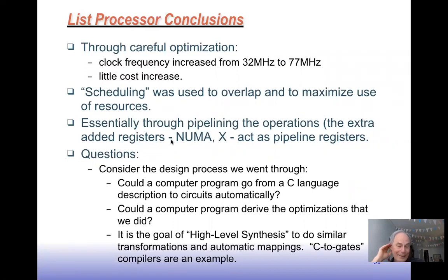There's something called high-level synthesis, which is different than logic synthesis. When we do logic synthesis, we start from behavioral descriptions in Verilog, which don't have these loops. That's mainly the big difference. Logic synthesis will go to logic gates and LUTs from some behavioral description.